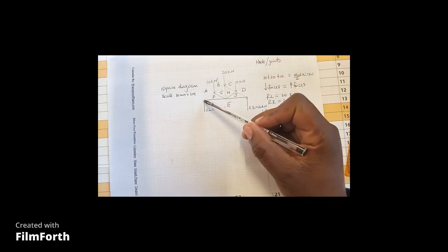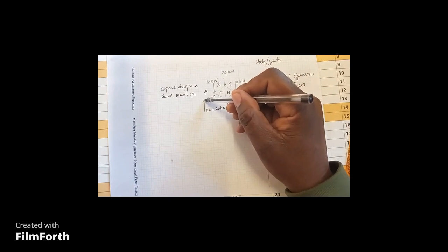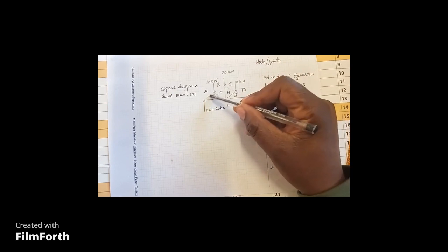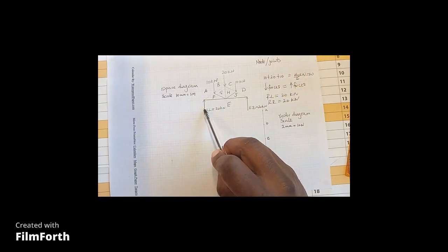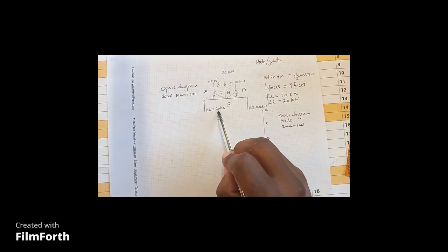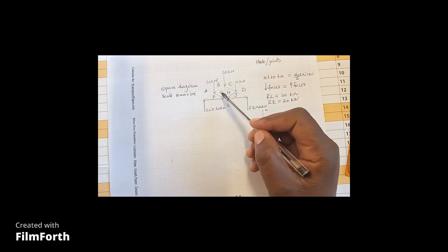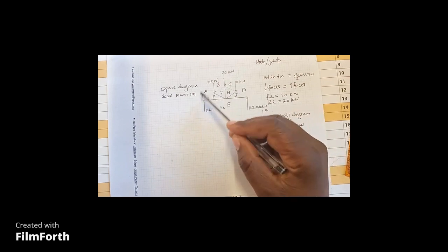If I come here, for example, I am calling this a point or a joint or a node, and already I do have first force, which is this one. I have AF and I have FE, which is this member. So you realize already that I know the magnitude of my reaction left, which is 20. I only don't know the magnitude of this member and the magnitude of this member. So already I don't have more than two unknown forces, right? Which is a different scenario.